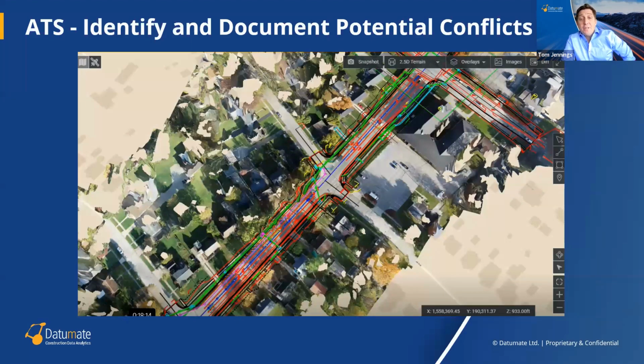Before setting foot on the job site, he can use the annotations tool to document all of these visible conflicts on the project. The annotations tool provides a screenshot of each conflict, comparing the 3D model to the as-built file, so that visualizing the problem is easy. He hands over a PDF report identifying all of the conflicts to the owner and architect to fast-track pre-construction meetings.